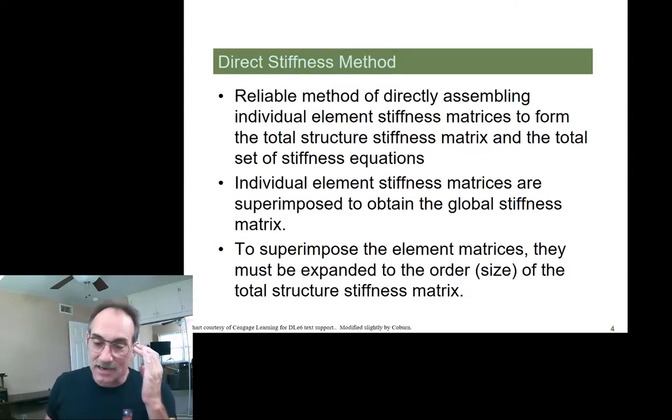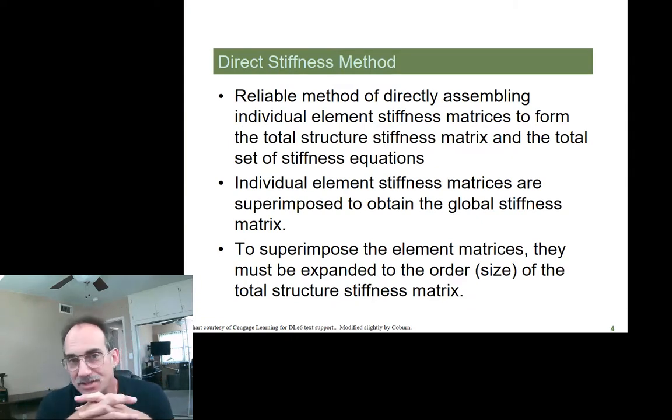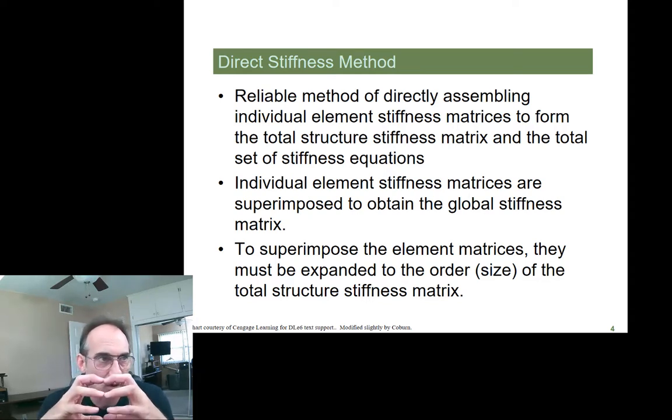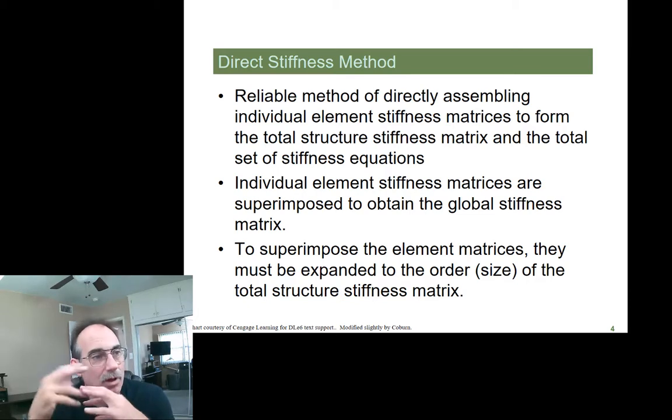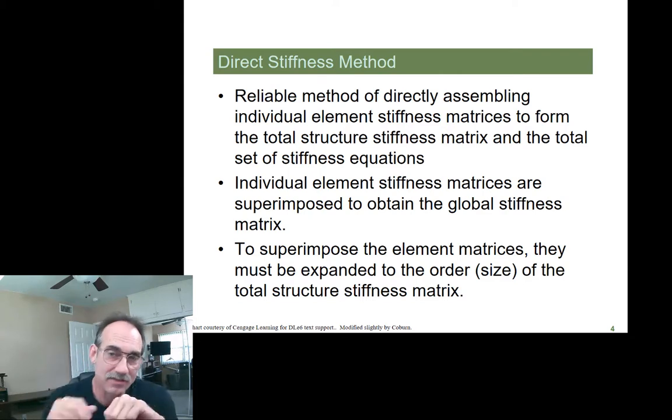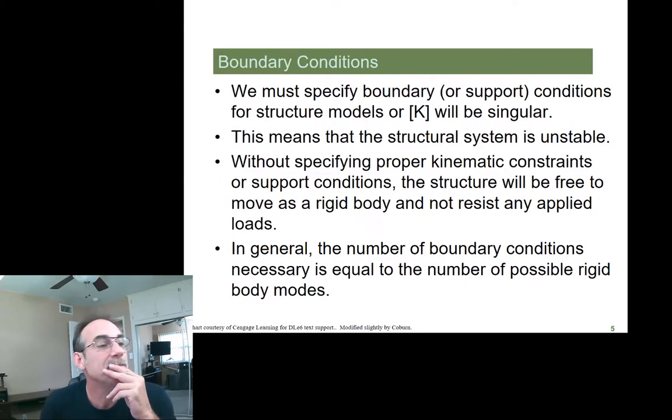So now there's a number of different methods for doing finite elements. The direct stiffness matrix that's shown here is one where we're going to assemble a global stiffness matrix, and then impose our boundary conditions and our external forces and solve. Okay, this is very direct. Sometimes we need higher methods to do this.